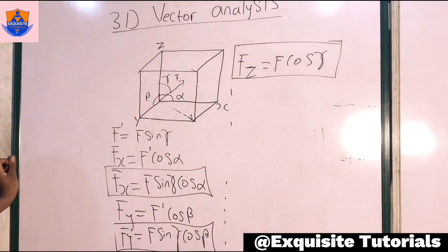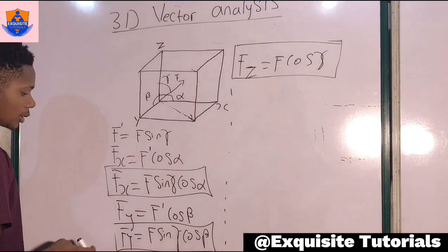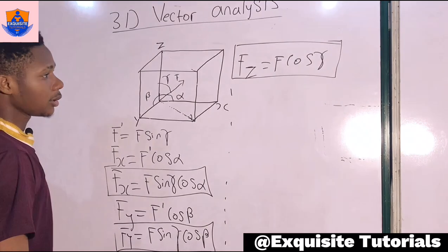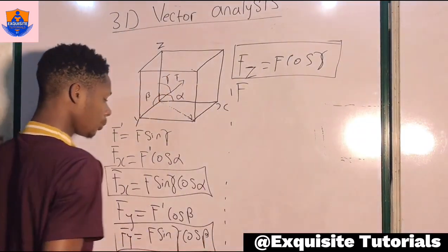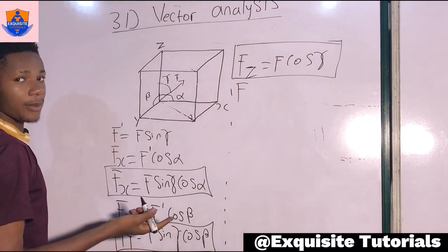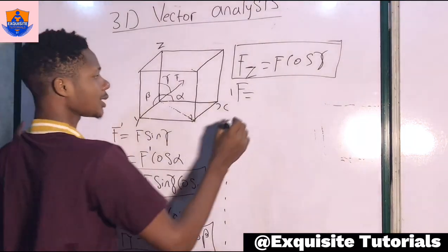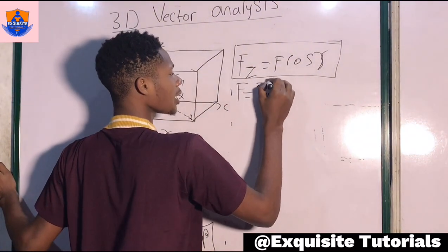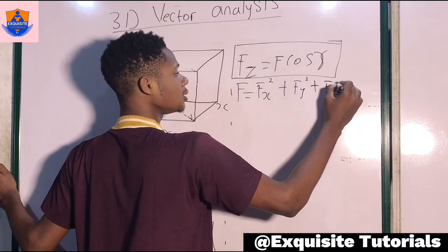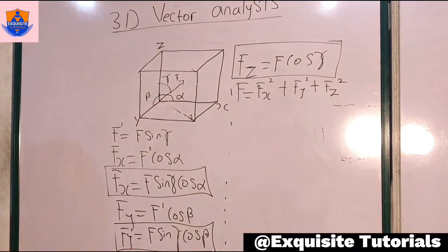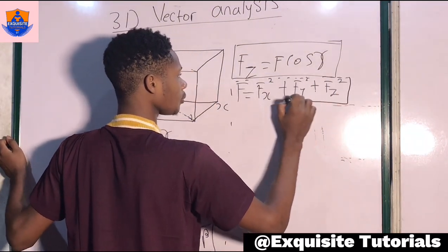Now here we're having the resultant vector on the z-axis and on the x-axis and on the y-axis. Let's say we are to remove it from the Cartesian form. The total resultant vector becomes the square root of the sum of the squares, like applying the Pythagoras theorem. So we're going to get the square of each component. That will give us fx squared, fy squared, fz squared. Okay, this is what we are going to get. So the resultant vector is given as what we are seeing here.